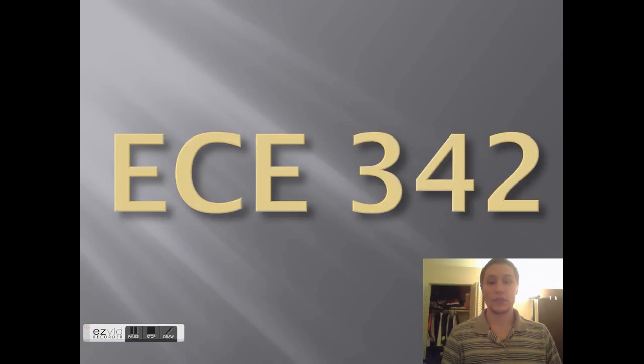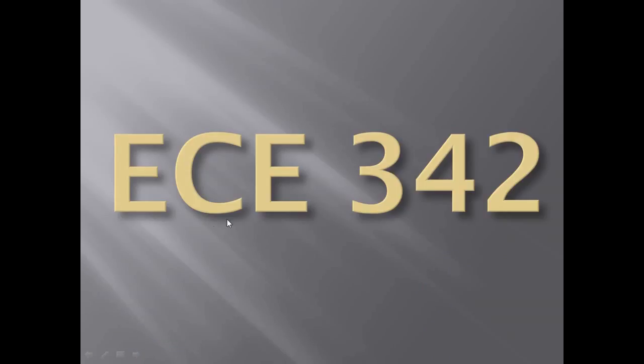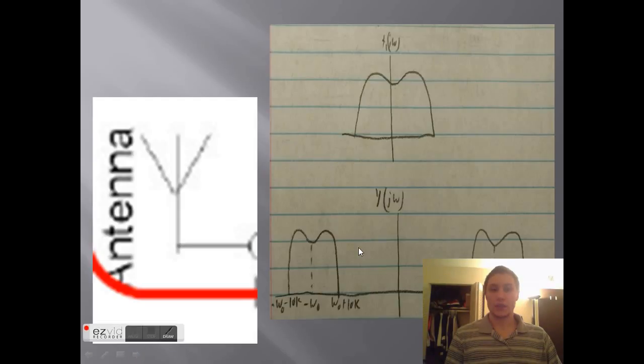Now, the last thing is 342. The main thing in 342 that we talked about is this antenna. An antenna is usually going to be the biggest part in your circuit because you can't necessarily shrink it down. That is because it needs to be able to receive the entire wave. A lot of times you can shrink it a little bit by having a quarter wave or a half wave or something of the sort.